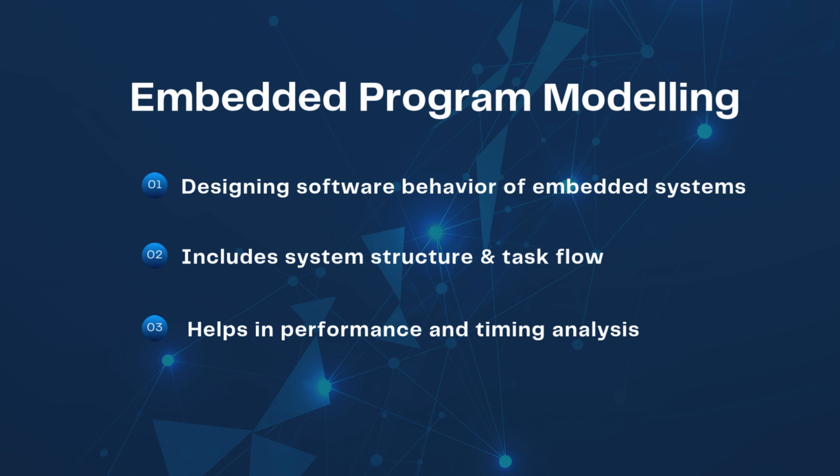Now let's talk about embedded program modeling. Embedded program modeling focuses on designing the behavioral structure of embedded software before implementation. It includes modeling system structures such as task flow and timing constraints using techniques like finite state machines, data flow models, and task graphs. This helps engineers analyze performance, latency, and scheduling feasibility before actual development happens.